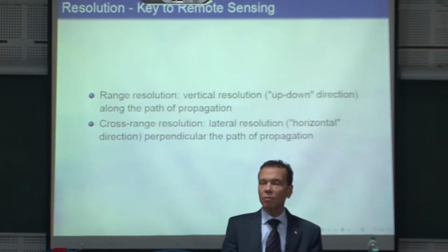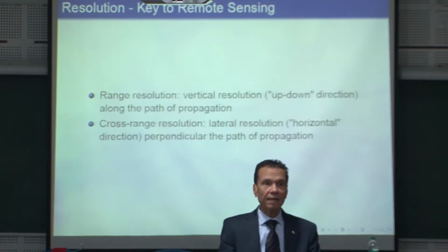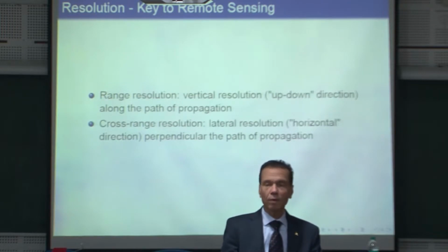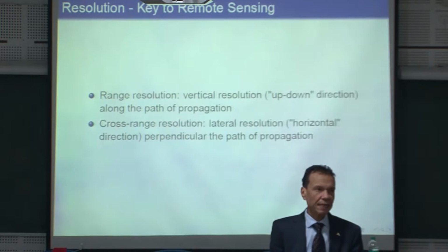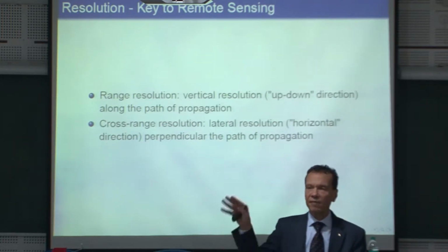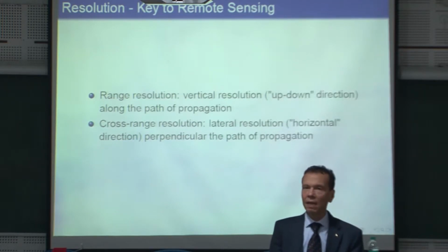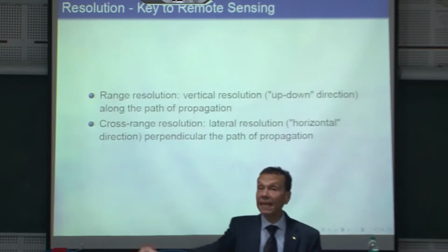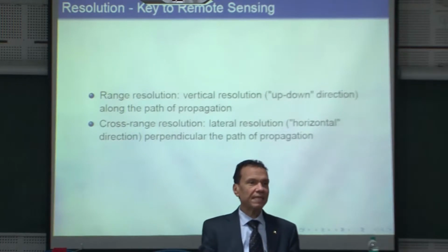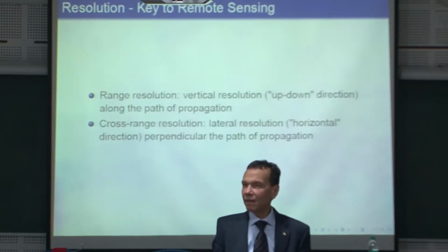In order not to have a headache from that, there are methods for subtracting this big amount of reflection. This is also signal processing. You can say, let me assume first that I don't have an object. I have an air-sand interface, and I calculate the reflection due to the air-sand interface. And I subtract it from my measurements. So in this case, I get my measurements clean.